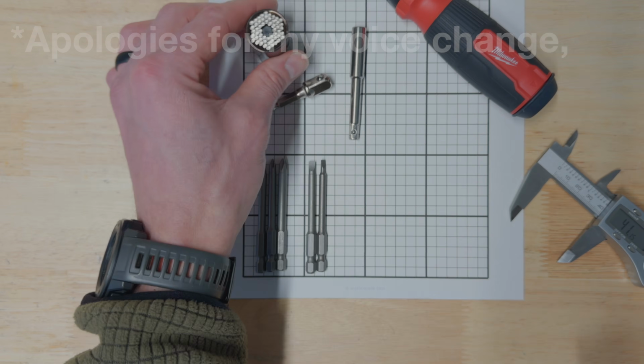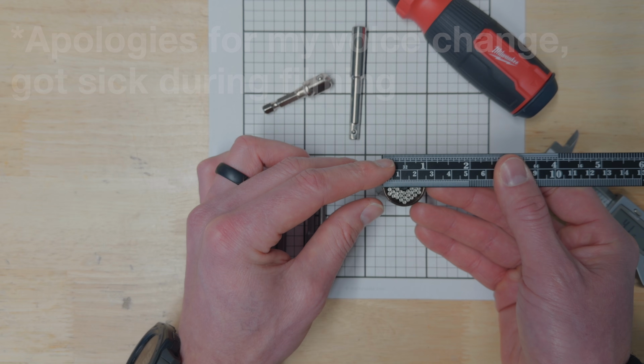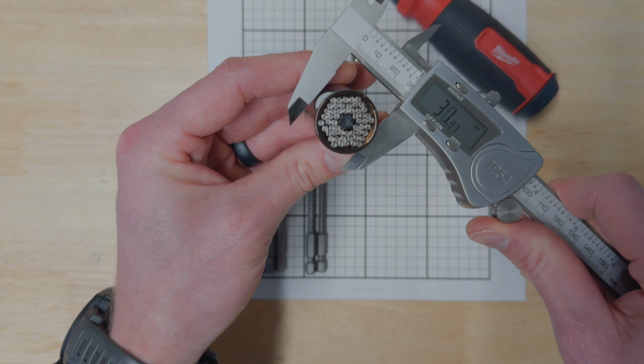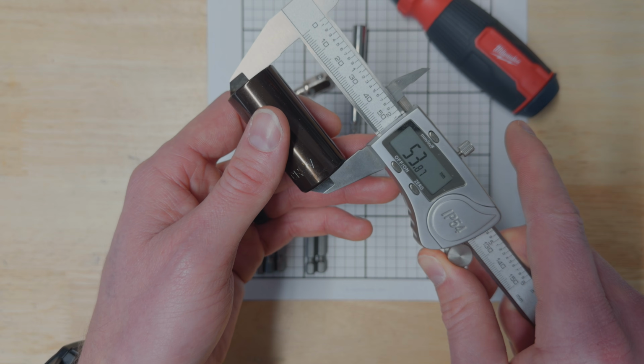You can also use a revolve on certain tools to get a highly customized cutout that will fit your part nearly perfectly. For starters, this is where it's really helpful to have a set of calipers or even your ruler or tape measure to get an accurate measurement of the tool you want to revolve. Simply take measurements of your overall part, which I'm doing here first to the universal socket I have, and get a good idea of the diameter and the length of the part.